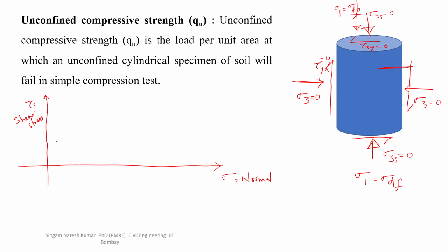What do we need to draw the Mohr circle? Sigma comma tau, two points which are the extreme ends of the diameter of the circle. If you take those two planes which are perpendicular to each other, they will become the end points of the diameter. First I will take the point on this plane: sigma 0 comma 0, that is here.